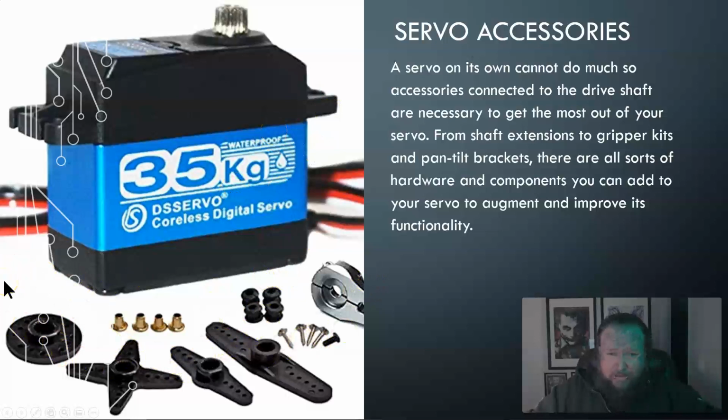A lot of times when you buy servos, or if you have ones with kits, they'll come with these kind of plastic tops here that have different holes that can be screwed in. There's usually a little spot for a screw in here so that you would take one of these bottom pieces, slot it in, and then use a screw that's provided with it, and a very small screwdriver, to lock it in place so it doesn't come apart. Most things we're doing, you can just connect in. These holes that you're seeing through here are so that you can cut or stick or tie things in through it to actually attach stuff to this. So maybe metal wires, so that when this arm moves, it causes something else to move.